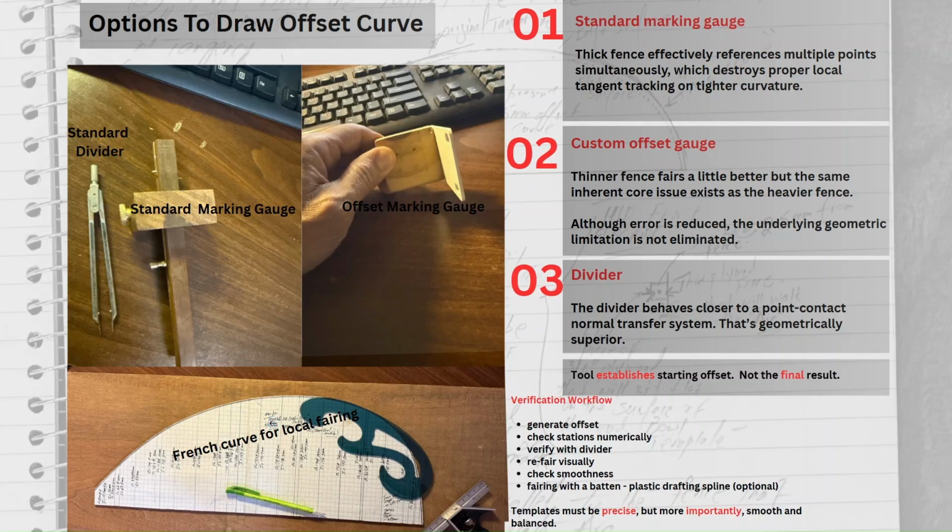So again, if you had a CAD package, and I mentioned it in one of my earlier episodes, if you use something like Fusion 360 to get that offset, it's a click of a button. But I think it's important, at least for me, that I do it by hand, at least my first pass, so I get a feel of the geometry, deal with these constraints, and get a good feel of what works and what doesn't work.